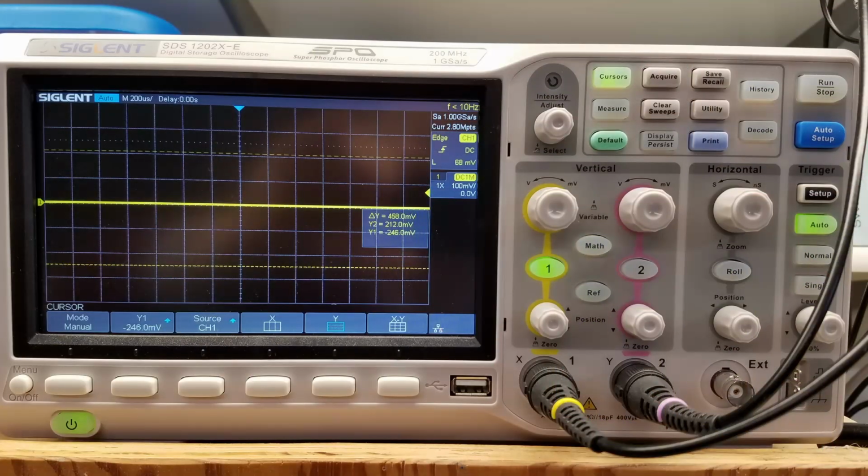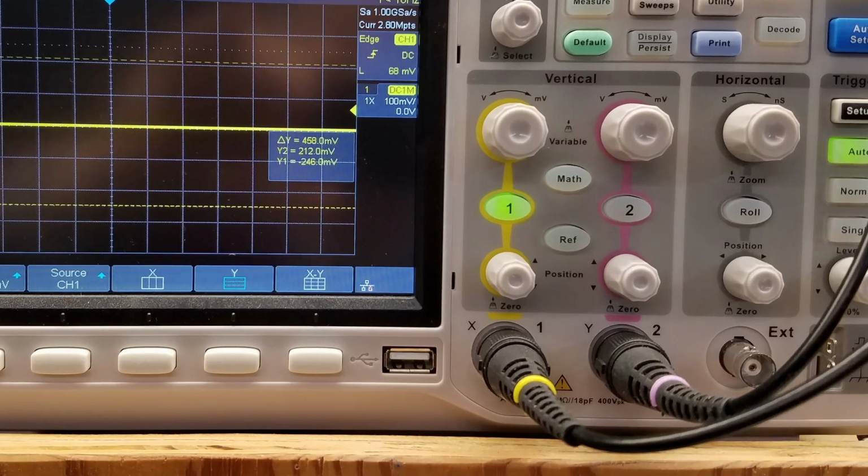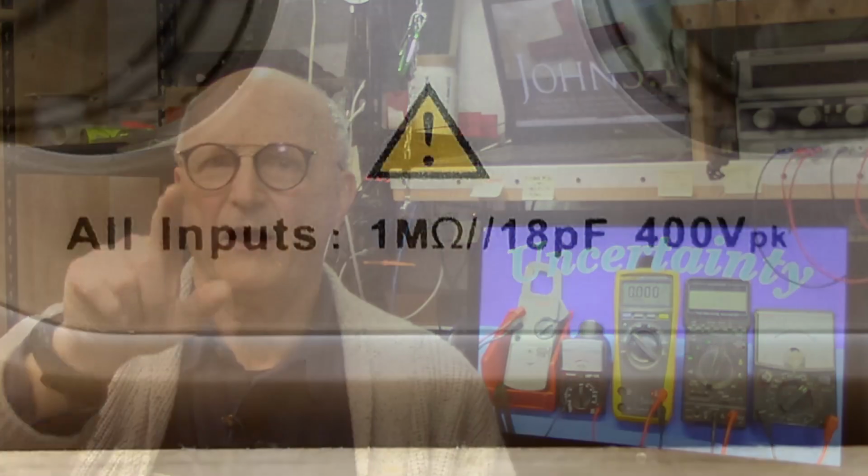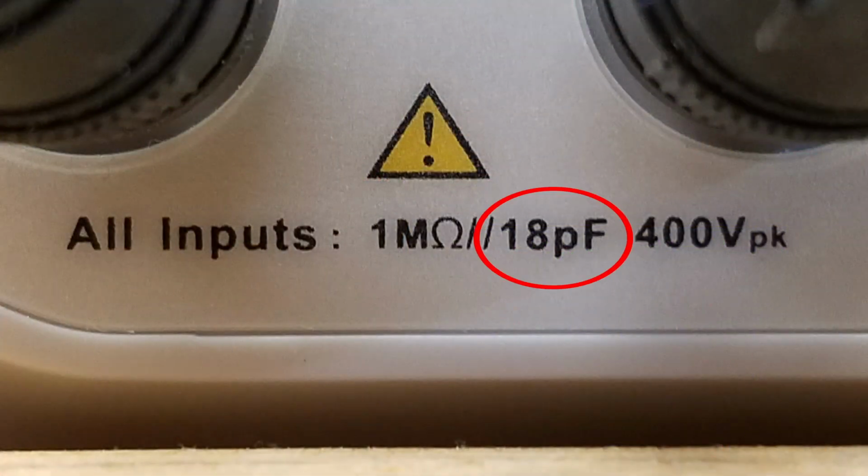Now, these sorts of concerns do not just apply to multimeters. Consider an oscilloscope such as my Siglent. This one, like most oscilloscopes, has something on the order of a 1 megohm input impedance. And this seems quite sufficient, but in some situations this can still load the circuit in question. Now, also be aware of the capacitive loading of the input of an oscilloscope and other similar devices when working with AC circuits, especially when thinking of RF measurements.